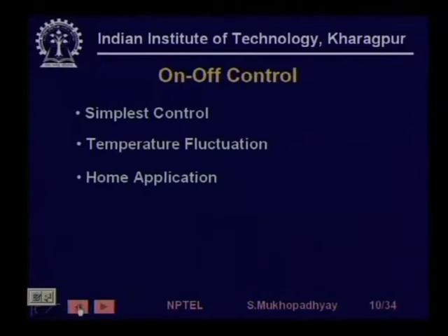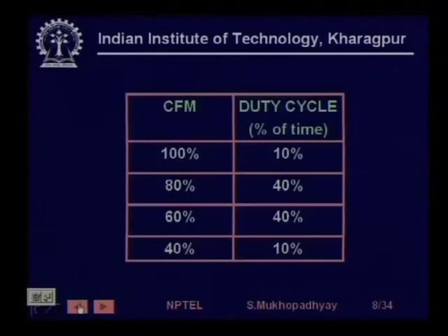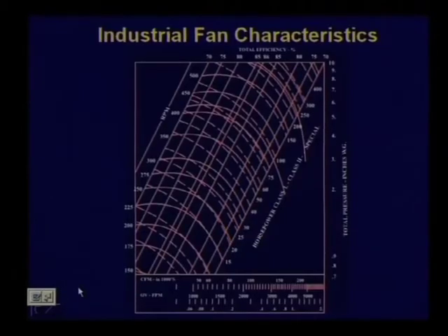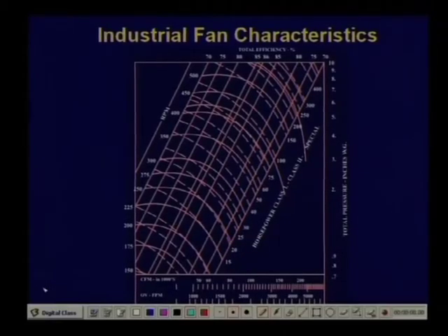So I am going back to the fan curve just to show you. Yes, so we are at the fan curve. Actually, this has been calculated with a fan RPM of about 300. So this is the 300 curve, the constant RPM 300 curve, and we are at 100%. So this is somewhere over here.